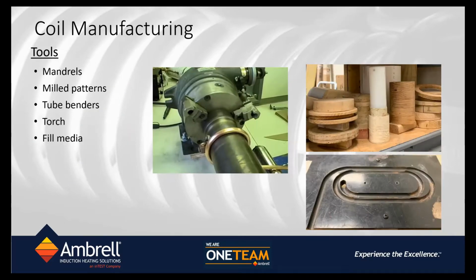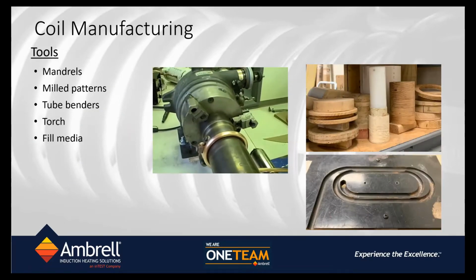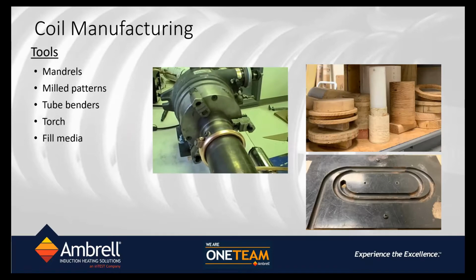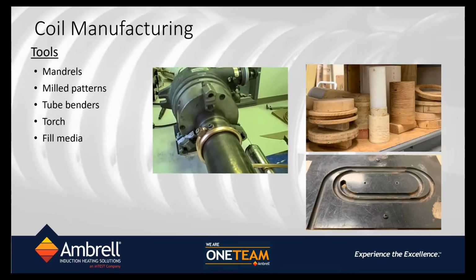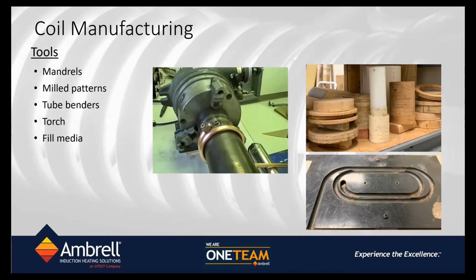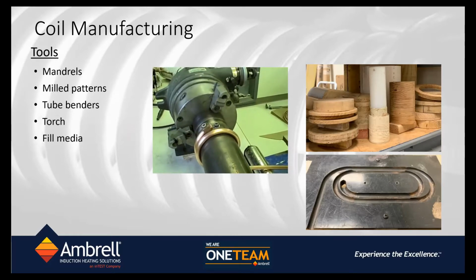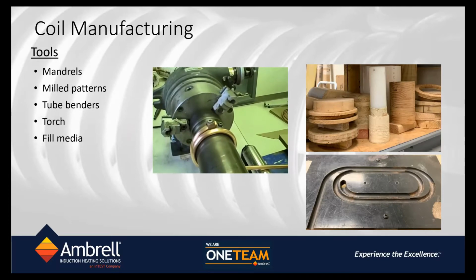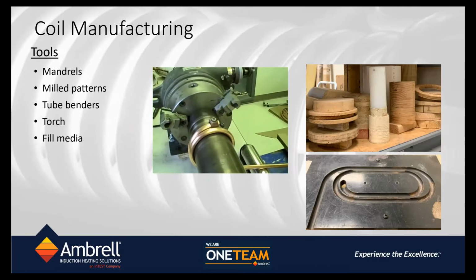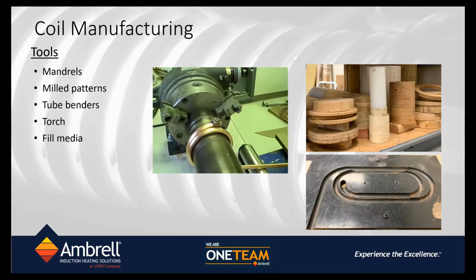Then to wind the coil, you can incorporate either wooden mandrels, shaped wooden mandrels, or milled shapes where you can lay in the copper tube to build the coil, or you can have automated setups like shown here to wind simple round type coils repeatedly.